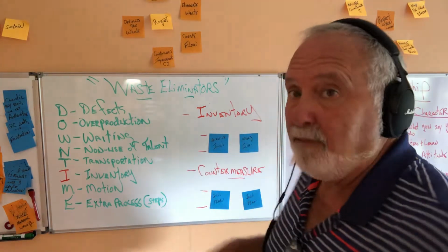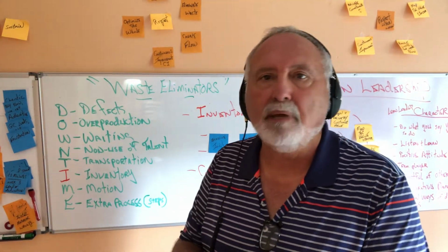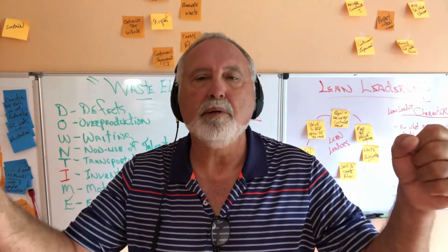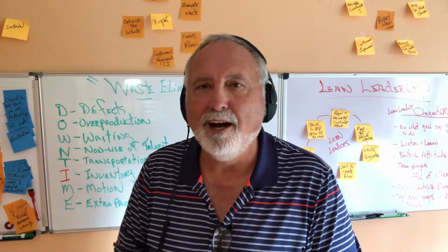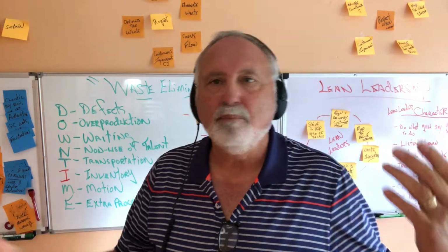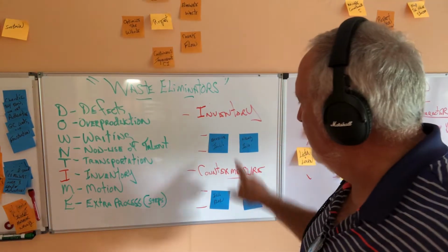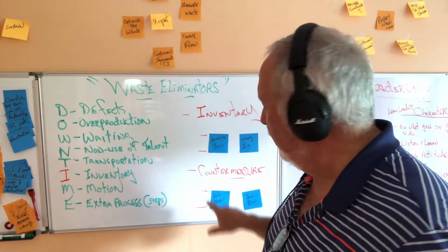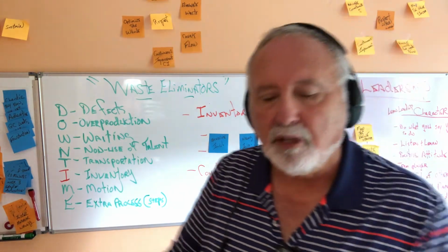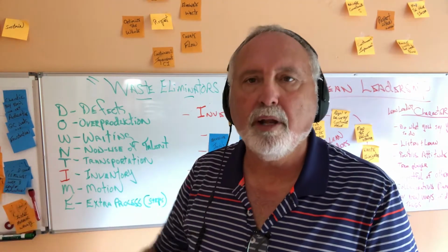I have to manage the inventory, that's waste. We're not in the business of managing inventory or warehouse manager. We're in the business of getting material installed in the building, right? That's value in the eyes of the customer. It's not value every time I've got to move material two, three, four times around the site. So for excessive inventory, the countermeasure is I need an inventory plan. What's my just-in-time plan? It's going to be tied to prefabrication. It's going to be tied to deliveries and how I transport it, so transportation.